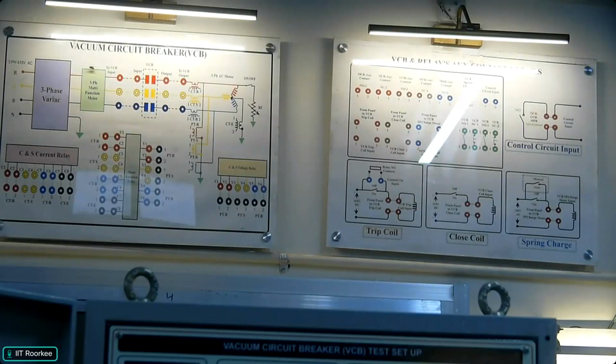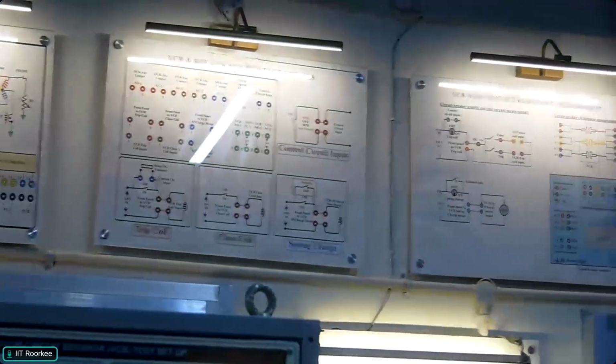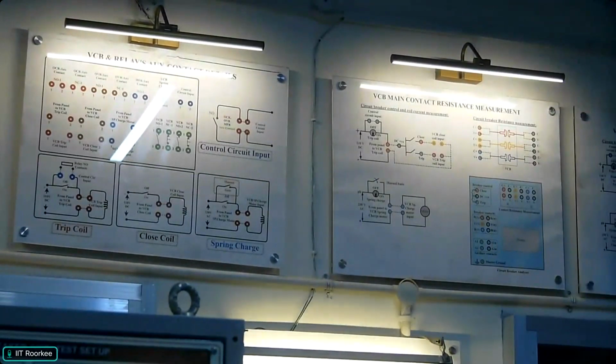I have already told that the spring charge is connected through the close coil. But if it does not work through that, we also have a manual button, so through the lever we need to charge the spring manually. Earlier this condition was the closed spring. Now we can change it